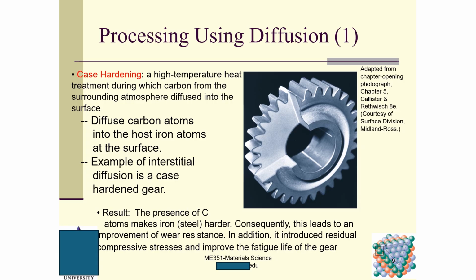I hope what I said makes sense to you. And I want you to know what benefits we can have from case hardening. First, we enhance the surface hardness of the specimen in case hardening, and so we can have better wear resistance. Second, we will have better fatigue life of this specimen because we induce compressive residual stress.